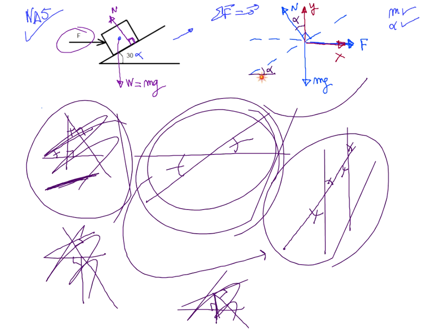And the second question you ask yourself is, is this leftover line perpendicular to my x? If it is, the angle is between your force and the x. If the other line is perpendicular to your y, then the angle is between your force and the y. You can never get it wrong if you follow this two-step process. And it's important because if you get the angle wrong, then I can just stop here. I don't have to look at any of the rest of your work. I know it's going to be wrong, and you cannot get any points.